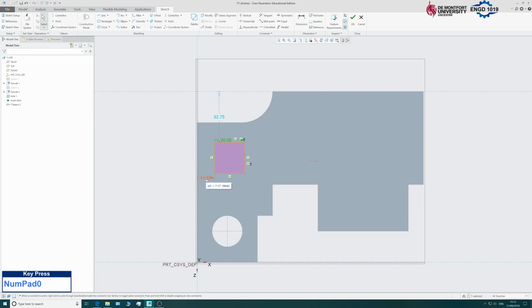The distance from the back wall is 10. Okay, so it's put in a reference from the top. We would like a reference from the bottom here. So we'll go dimension from this bottom edge, hold control, click the next line, and then middle mouse button. And that height should be 60. Okay, now we add in some circles. So there's a circle here.